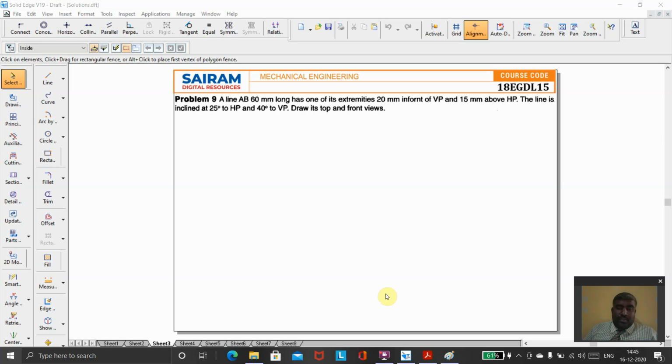Hi students, in this video we're going to continue the problems on the projection of lines. So let us consider a problem. A line AB 60 mm long has one of its extremes at 20 mm in front of VP, 15 mm above HP. The line is inclined at 25 degrees to HP and 45 degrees to VP. So draw its top and front views.